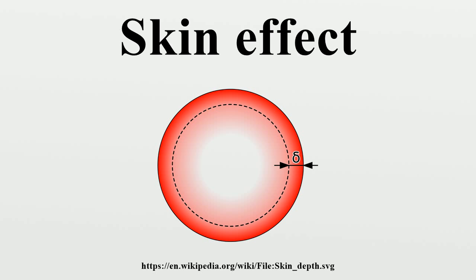Note that the inductance considered in this context refers to a bare conductor, not the inductance of a coil used as a circuit element. The inductance of a coil is dominated by the mutual inductance between the turns of the coil, which increases its inductance according to the square of the number of turns. However, when only a single wire is involved, then in addition to the external inductance involving magnetic fields outside of the wire, as seen in the white region of the figure below, there is also a much smaller component of internal inductance due to the magnetic field inside the wire itself, the green region in Figure B.